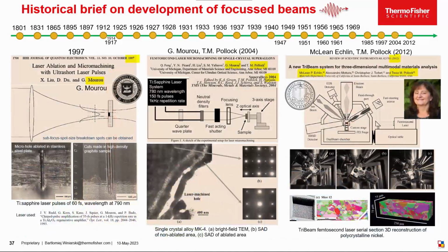The precise micromachining using USPL titanium sapphire laser was explored by Gerard Marot and co-workers in the subsequent years. In 1997, he published a paper presenting the first laser setup designed for micromachining with a 13 micron narrow focus deep red laser producing 60 femtosecond pulses. The micrographs on the bottom left show surface cuts produced by his laser setup.